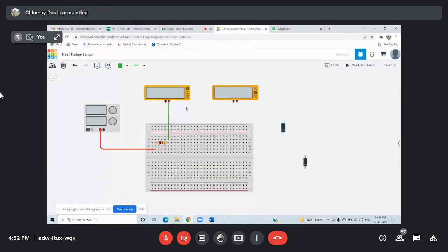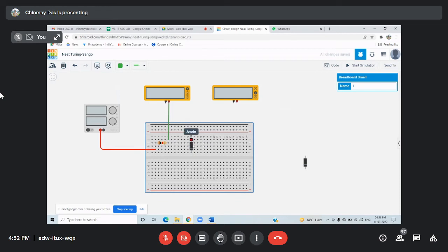So listen, the negative of the ammeter has to be connected with the anode of the diode. Okay. So first I connected the diode at the breadboard. I cannot connect like this because my anode and cathode will get shorted, as the vertical line is internally connected. Again, I am repeating, all of you listen to this carefully, because you are going to design all the circuits in your upcoming experiments on this breadboard and on Tinkercad. So this one is really important.